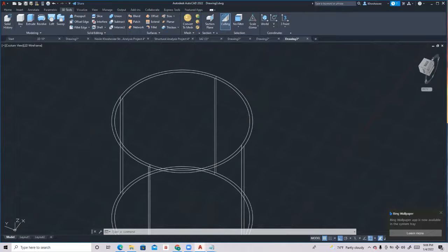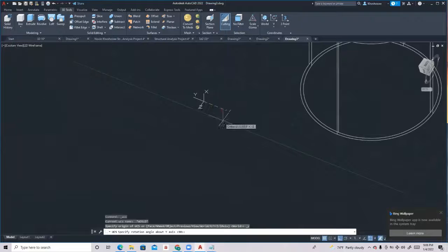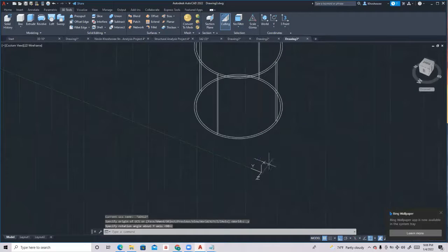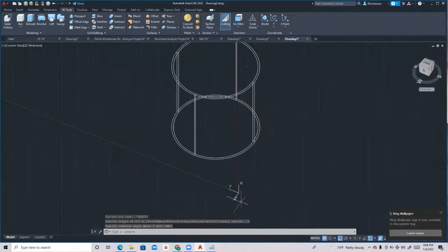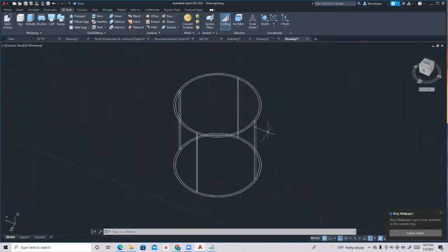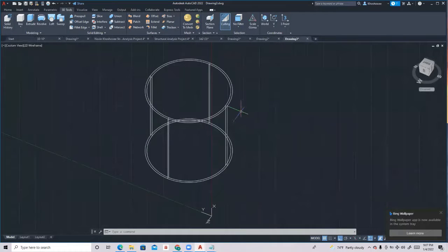So I can, for example, change it here, and as you can see, I can play with it. Let's say I put my Y here, and my X is our depth now, and our Z is coming toward me. One thing you have to pay attention to is that normally in AutoCAD, with the 2D tools that we have, we cannot draw on the Z plane.